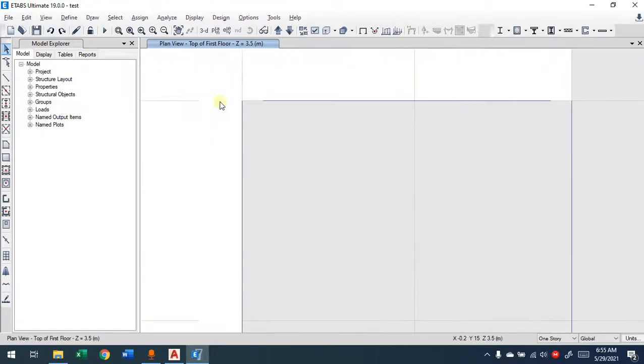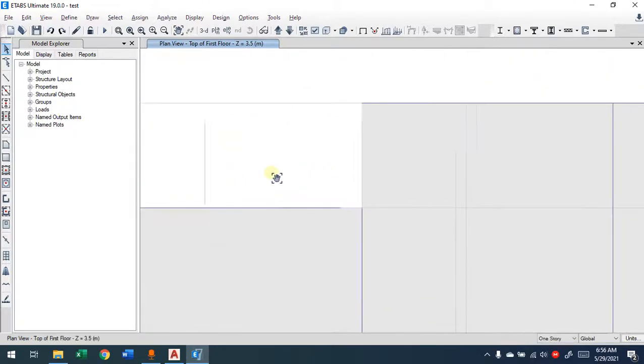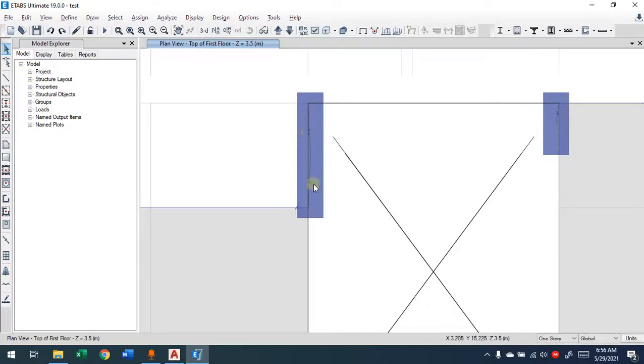Now the same thing goes in the Autodesk family. You have this selection, where you go from right to left or from left to right. Now, left to right, only things within the area will be selected. Let's say I want to select these joints here or those links here. I'll try to put the links within the box, and you'll see they will be selected. So I can see it here, 4 joints, 1 frame, 3 links selected. The things that are within the box will be selected.